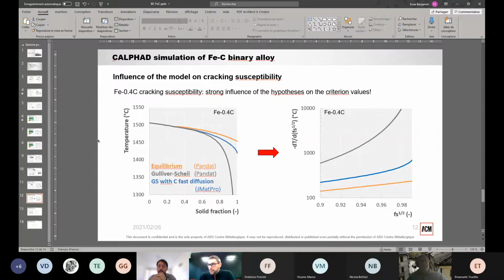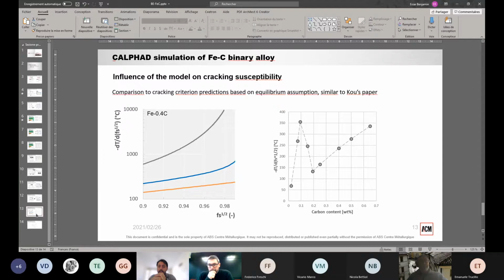Tayfun, any remark? Federico, any remark on that? Yeah, I agree with Benjamin. If you deal with steels, you gotta deal with diffusion, because you have different alloying elements with different sizes. Interstitial diffusion, substitutional diffusion. If you are just dealing with substitutional diffusion, then Scheil would work fine. But if you have both, then you need to consider different diffusion mechanisms.